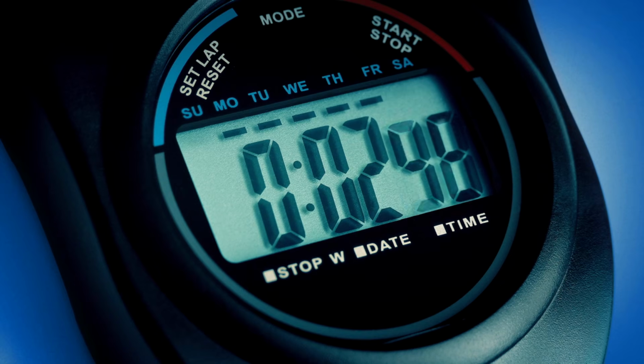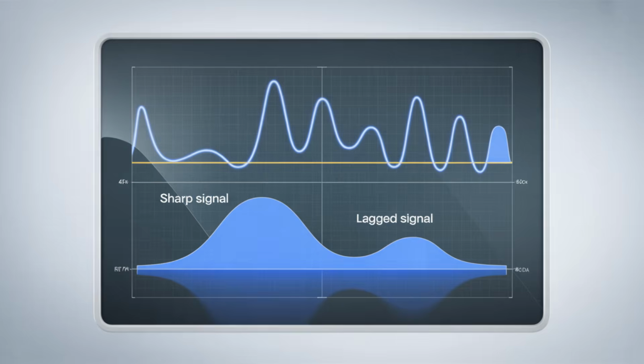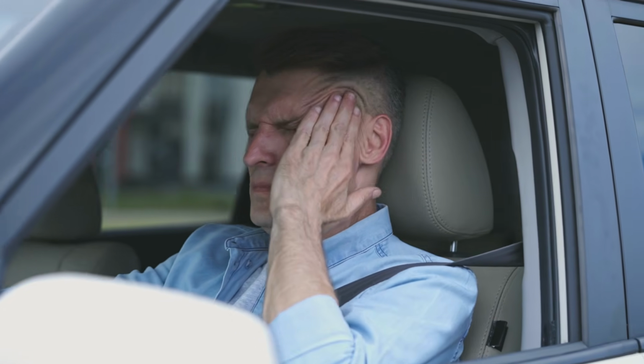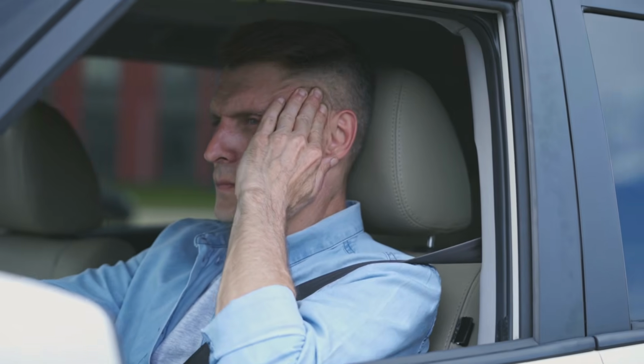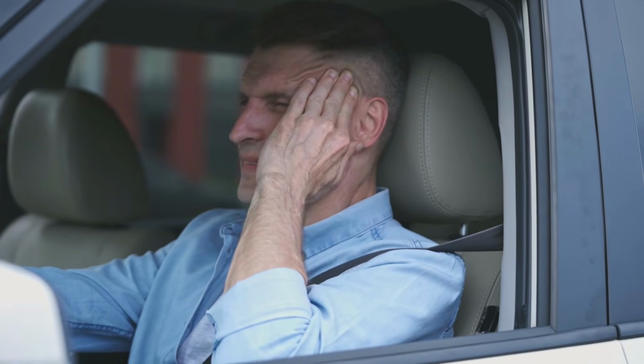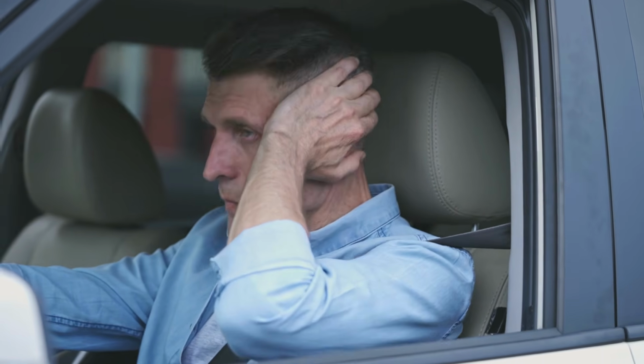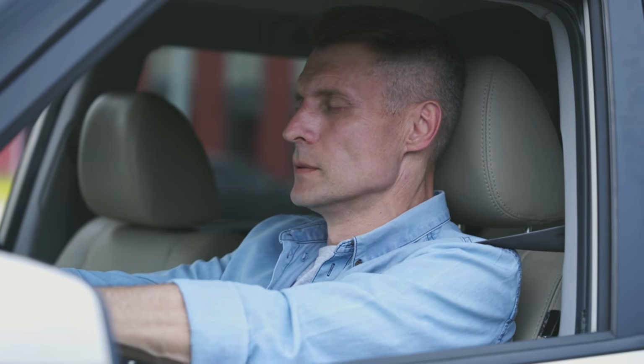The millisecond voltage delay that a fouled sensor introduces, the lag between actual airflow change and reported airflow change, also degrades throttle response. The engine's reaction to a sudden acceleration input is governed by how quickly the ECU can see the increased airflow and respond with additional fuel. A sluggish sensor signal means a fraction of a second delay in that response. It is the feeling of the engine taking a moment to wake up. Most drivers attribute it to the transmission or the engine being worn. The real cause is a sensor smaller than your thumb, coated in invisible residue.